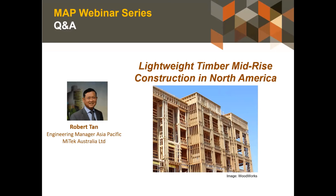Okay, there are three contributors to shortening. Obviously, one is timber shrinkage. If you close in your building early and keep it dry, the sooner the better, because then your timber would not shrink as it dries. So if your timber is nice and dry when it's all closed in, obviously that helps, and naturally it should be anyway. Shrinkage is one. Creep is the other, and creep is often related to shrinkage as well. And that might take its time, but that's something you have to deal with.